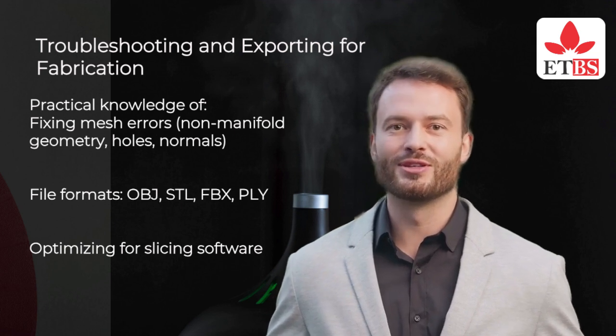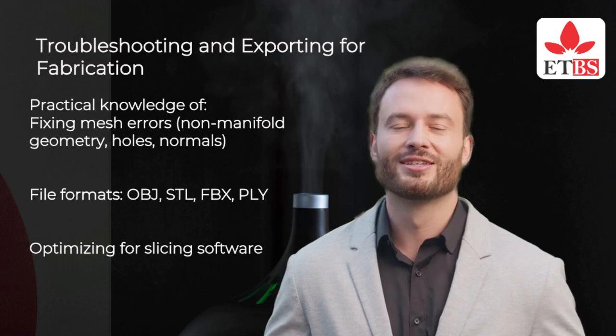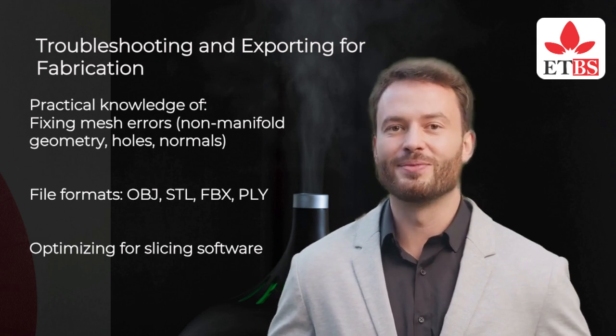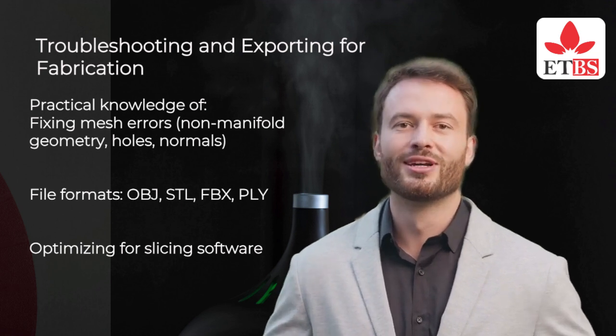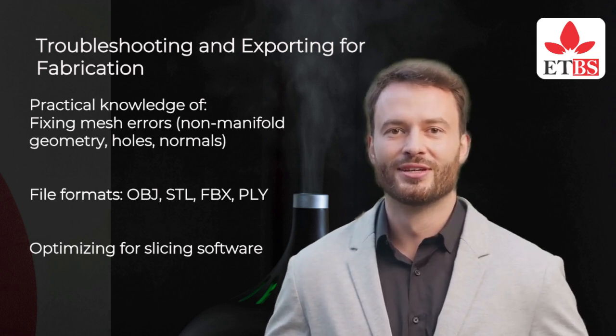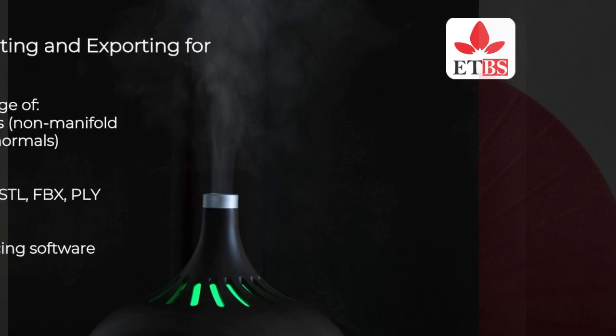Troubleshooting and exporting for fabrication: practical knowledge of fixing mesh errors, non-manifold geometry, holes, normals; file formats OBJ, STL, FBX, PLY; optimizing for slicing software, wall thickness calibration and supports; understanding print bed limitations and machine tolerances.